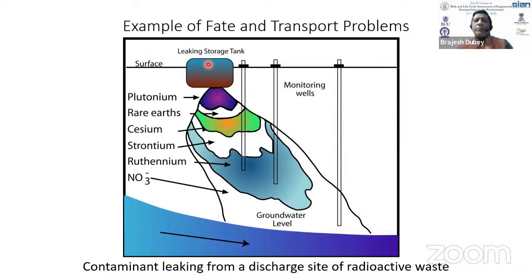So in terms of this radioactive waste, what is happening here? We have things leaking off, and as they leak, they are moving in the subsurface. Now, this particular region on the top is known as the Vadose zone. The Vadose zone is the unsaturated zone. Here, the pore spaces in the soil are filled with some moisture, but not 100% covered with moisture, so it has some soil air as well. Things can move, air can move around this zone.